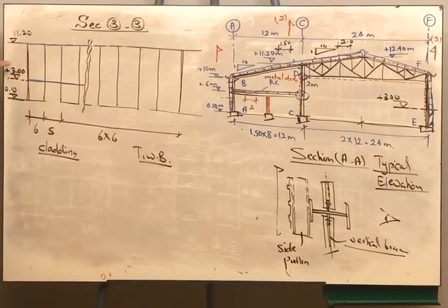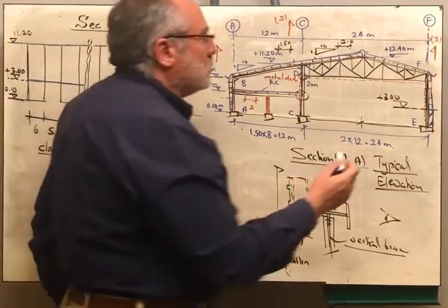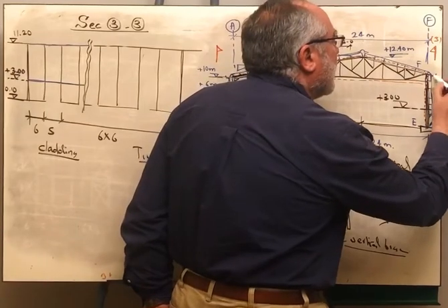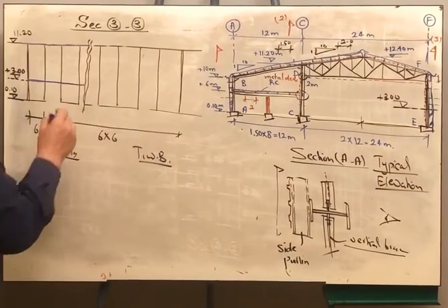This distance is 8.2 meters. We cannot have the spacing between the purlins 8.2. Again, it is from 1 to 2 meters. We decided in the previous lecture to take constant spacing of 1.75, and the last distance will be 1.2. So we are going to follow this here.